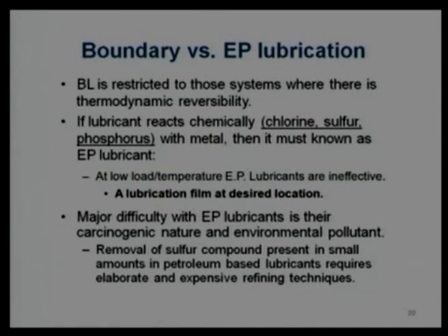But because of pollution, it has now been emphasized that petrol should be free of sulfur, or it should be below a certain limit, or the sulfur percentage should be at a minimum. It is costly in twofold. First, you require a process to separate the sulfur from the petrol.